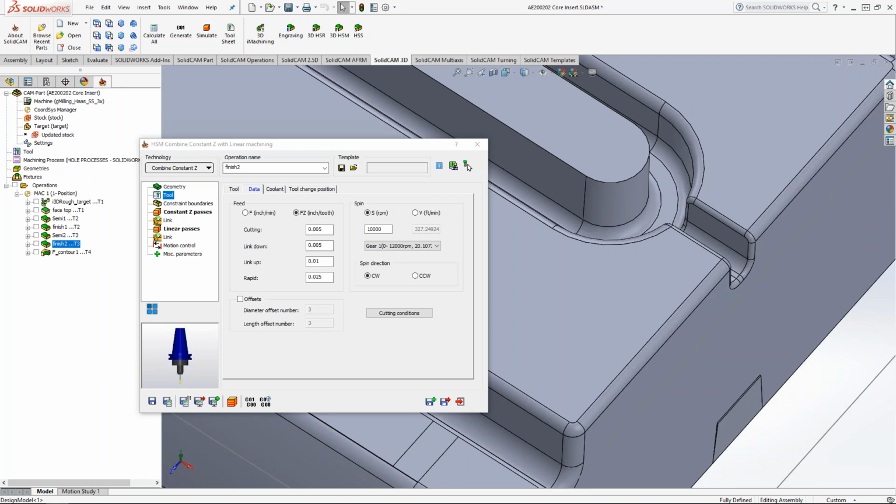Yeah, and you've got to think too, when you look at an entire mold, we haven't gotten anything too crazy here, but you're getting maybe 1 million different surfaces. In some of these molds, you're going to have to click on all those surfaces with HSS, whereas with HSM, all Scott has to do is throw a boundary around that, and it's fine. But like you said, HSS is kind of just that fine tune. So that leads on to the next one: would you say, in your personal opinion, HSM is more geared towards the mold work side of things?